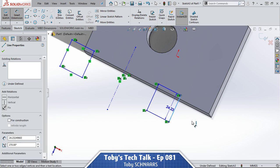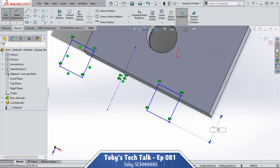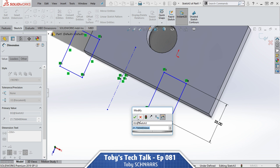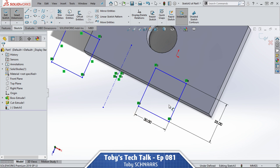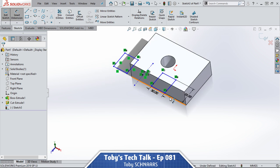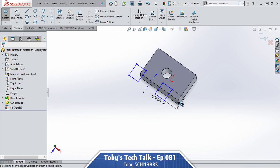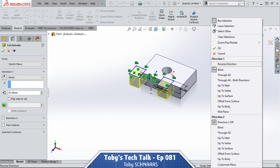And then when it comes to Instant 2D, what Instant 2D does is when you single click on a sketch dimension, it behaves very similar to Instant 3D. Meaning that you don't get the modify spin box that we see here, just the value highlights in blue, and then you can change the value. So I also turn that off, but again, that's just preference. It's not functionally superior or anything. It's purely preference, similar to turning off shadows in shaded mode. I turn it off, but it's not functionally better or worse. It's just what I prefer.